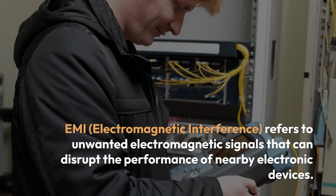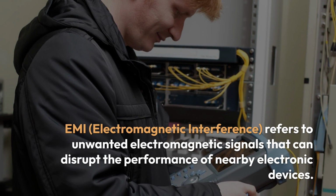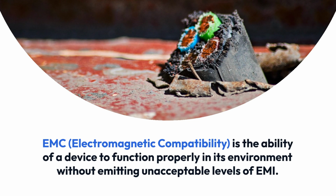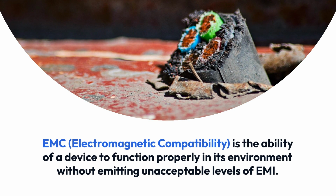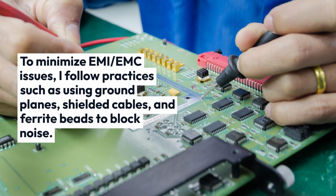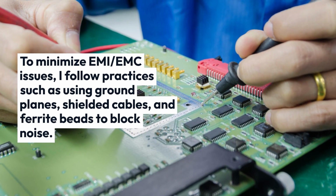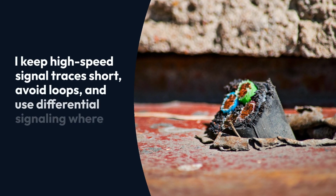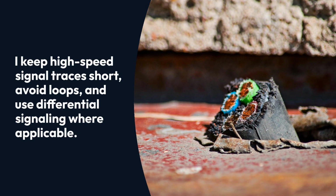EMI, electromagnetic interference, refers to unwanted electromagnetic signals that can disrupt the performance of nearby electronic devices. EMC, electromagnetic compatibility, is the ability of a device to function properly in its environment without emitting unacceptable levels of EMI. To minimize EMI/EMC issues, I follow practices such as using ground planes, shielded cables, and ferrite beads to block noise. I keep high-speed signal traces short, avoid loops, and use differential signaling where applicable.